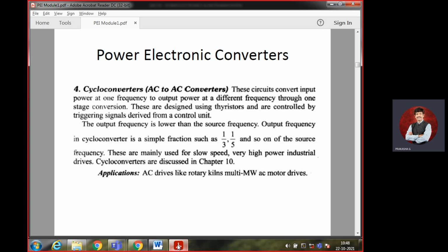Now the knob is rotated, so the resistance is reduced, maybe to 10 kilo ohm. Previously no current was flowing; now I have reduced it to 10K, so some amount of current is flowing and the fan will rotate at low speed.